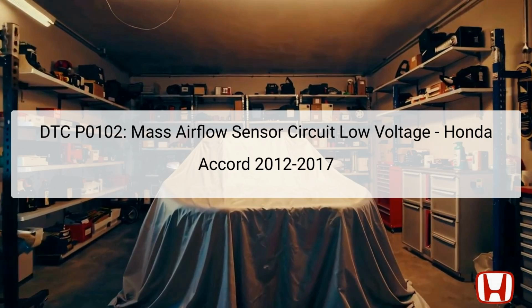For Honda Accord models from 2012 to 2017, the MAF sensor is a type of hot wire airflow meter that relies on an electrically heated wire. The engine's powertrain control module, PCM, which is an essential component for overall vehicle performance, measures the current required to maintain the temperature of this wire.